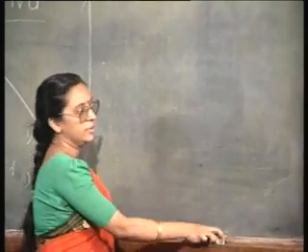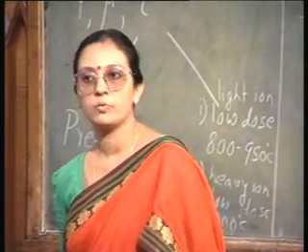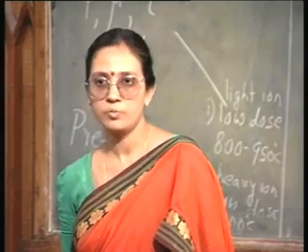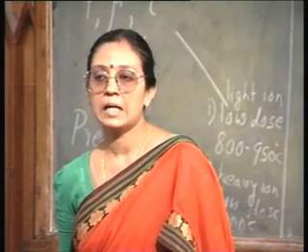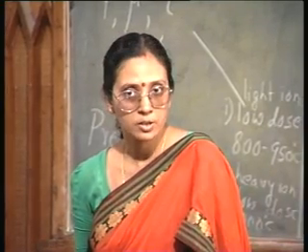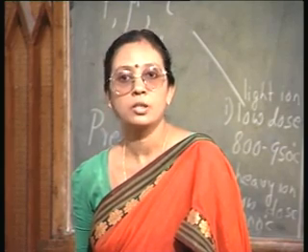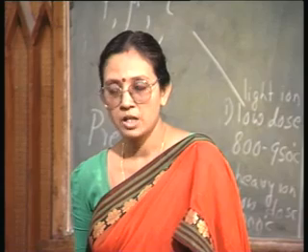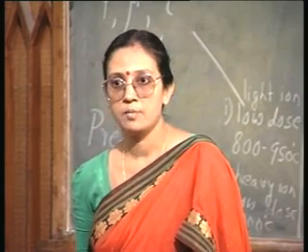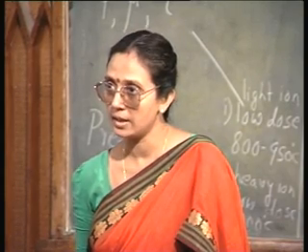Let us think about the two profiles. During implantation, the profile you had is a Gaussian profile. You have a Gaussian ion implanted profile. Okay? And now, when you are carrying out the annealing, you are not supplying any extra dopant material, right. So, it is actually a constant total impurity case, analogous to drive-in, right. I am not supplying any extra impurity, whatever impurity was put inside the semiconductor is still remaining there.